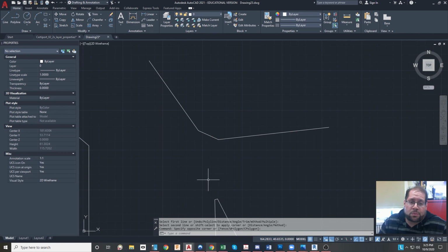So chamfering puts wedges on an edge, and fillet puts a rounded corner on an edge. You see rounded corners on pretty much everything. There's a rounded corner right here on my cell phone. That is both for aesthetics, making it look nice, but it's also protective of it. If I were to drop my cell phone on a surface, that impact, because of the rounded corner, is distributed throughout the surface area of the back of this object.